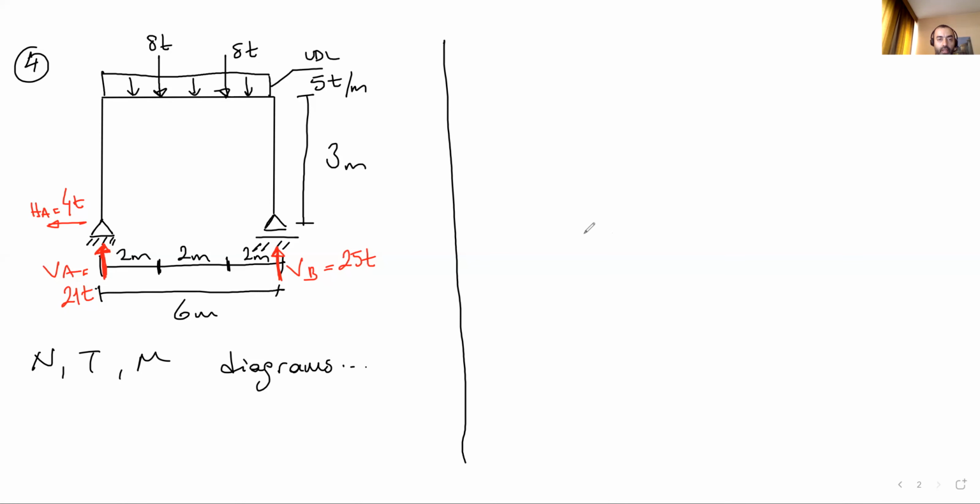Okay. By the way, when we start to draw the internal force diagram, what we do first, by the way, this is the wave direction. We draw the positive directions here as a reminder for us. If the axial force goes out, this is positive.